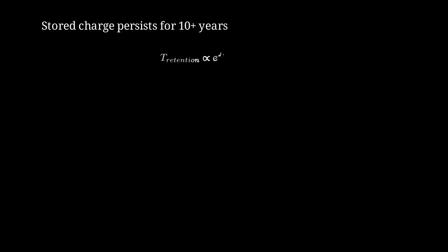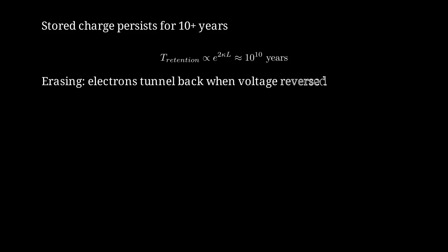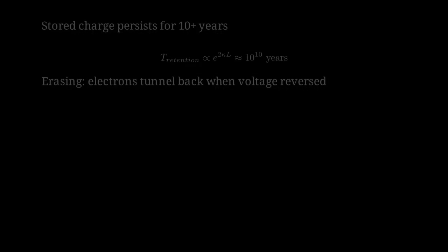The theoretical retention time is proportional to e to the positive 2 kappa L, which works out to billions of years for thick enough oxide. When erasing, applying the opposite voltage makes electrons tunnel back off the floating gate, resetting the memory cell. One of the most beautiful applications of quantum tunneling is the scanning tunneling microscope, or STM.